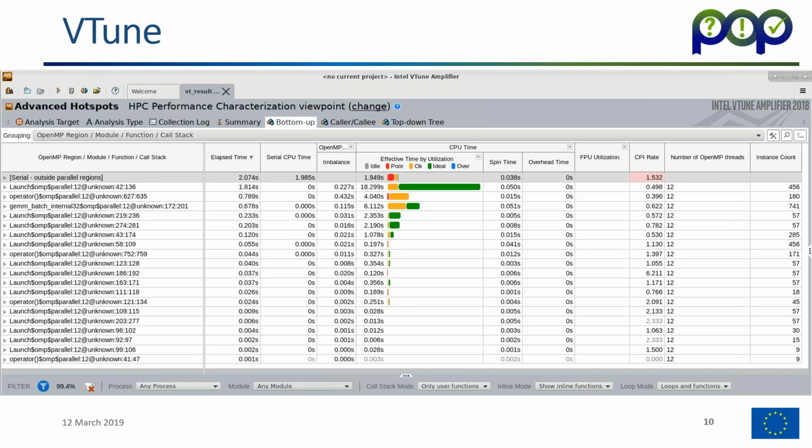What we found on this case study was we only needed to use one of the analysis types in order to generate all the metrics that we used to understand the performance of zCFD. In the version of VTune that we used, it was the advanced hotspots analysis. You can see in the top left of the screenshot on the screen now, in bold, it says advanced hotspots. I think this is VTune 2017 or VTune 2018.